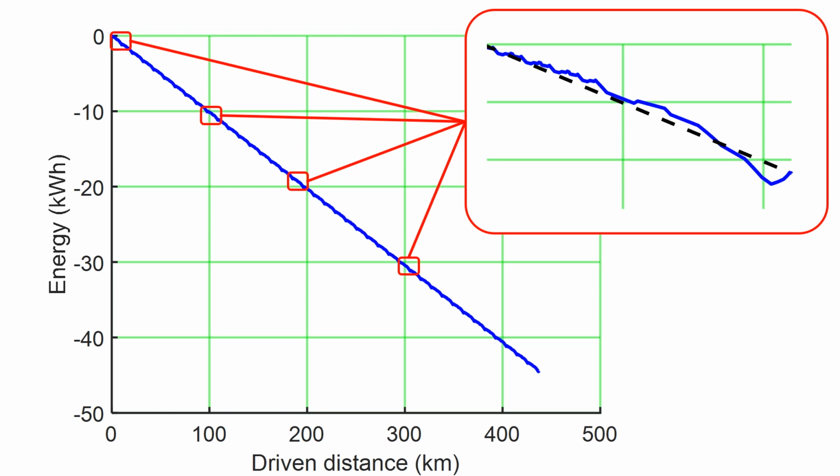So there are no good reasons to assume that demanding driving situations can only happen at certain segments of the 300-kilometer driving range. So we have to assume that every power level which the battery is required to provide can occur at any state of charge. In other words, the power demand is independent of state of charge.